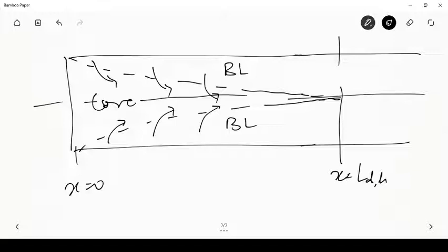The boundary layer has a restriction on velocities and cannot carry more mass, and that's the reason why the velocity at the center between the two boundary layers increases beyond the mean velocity, whereas inside the boundary layer it remains lower than the mean velocity.